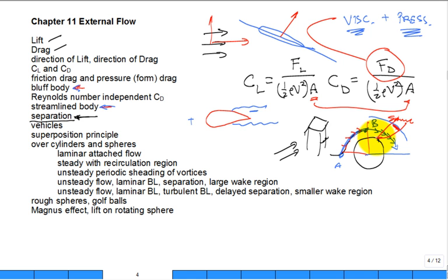And there's not a lot of dynamic pressure at the expense of the speed to recover the static pressure. Hence, you get such a severe adverse pressure gradient that you get reverse flow. At that point that you start to get reverse flow, that's the separation point, and then you develop a wake. That's this point of separation.